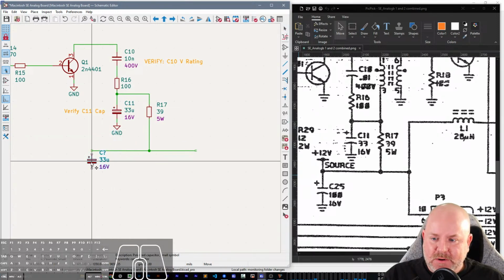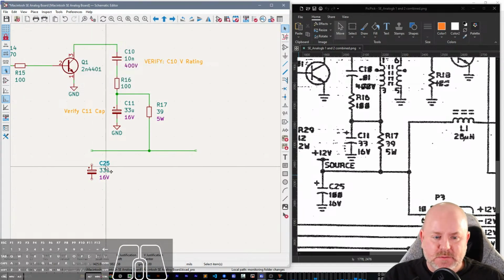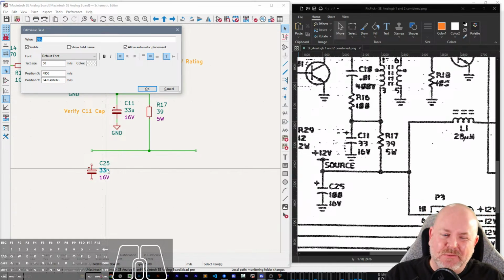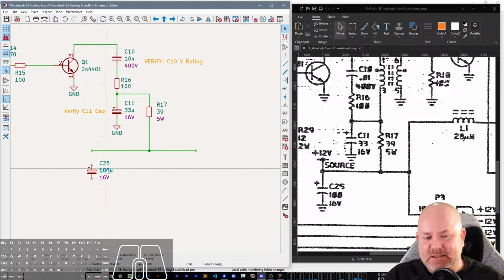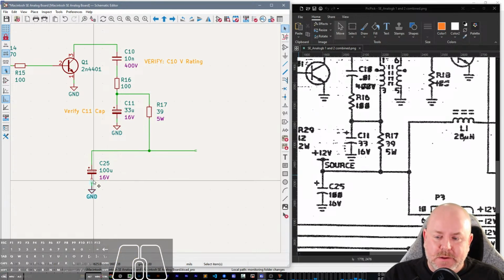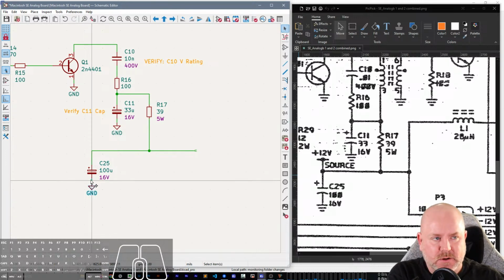When I was teaching electronics classes at Tech Shop, one of the classes I taught was a measurement class. I would show how to use a DMM, a bench power supply, and briefly go over how to use an oscilloscope. We didn't have enough time, but I tried to at least show people how to use the auto set button to get something on the screen. For the DMM, I would give them a capacitor, because the ones we had could measure capacitance.